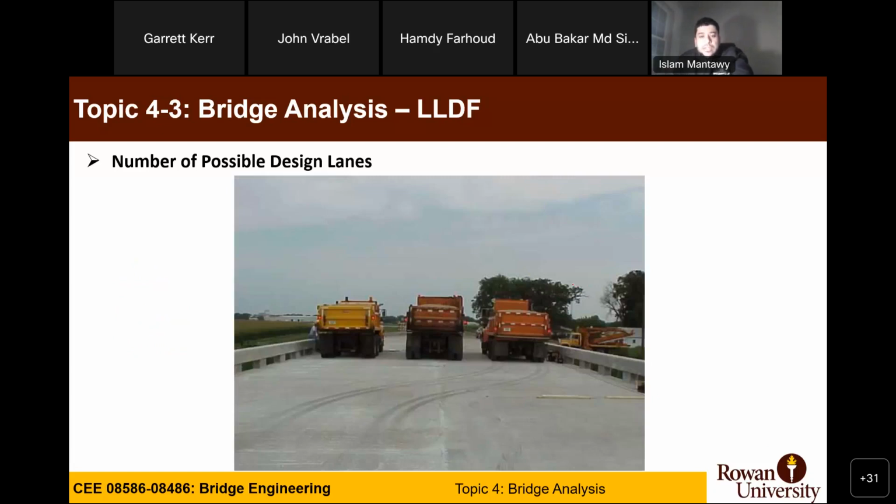And it is just a sketch of what's called bridge loading that we do sometimes for bridges. We bring those loading trucks and put weight on them, maybe sand or whatever, and we put them side by side to simulate the three-lane loaded case. But as we mentioned, because of the multiple presence factor, the probability of having them side by side is less than having one or two side by side.